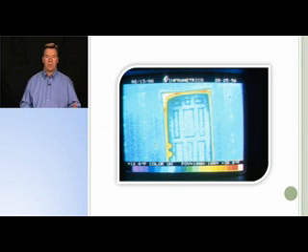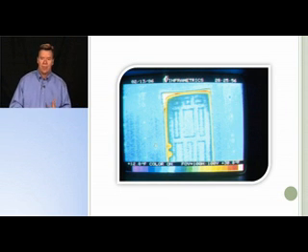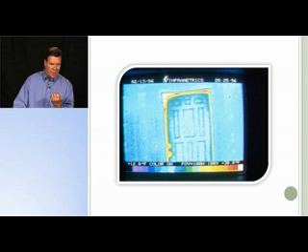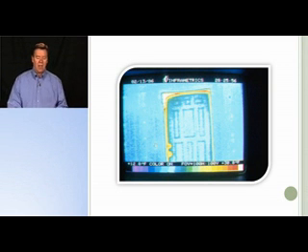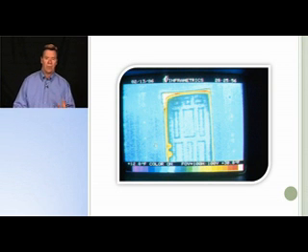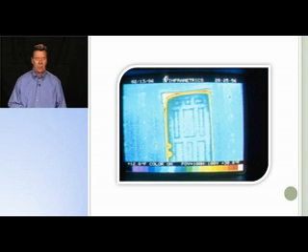When you look at weather stripping around a door, the reason that we weather strip is because oftentimes doors do not seal tightly, and so that becomes a very easy way for air to infiltrate into a home. When you look at this infrared image here, you can see that the white and the yellow areas around this door are leaking heat pretty well. So not a good thing. So we use weather stripping around doors and windows to reduce that heat transfer.